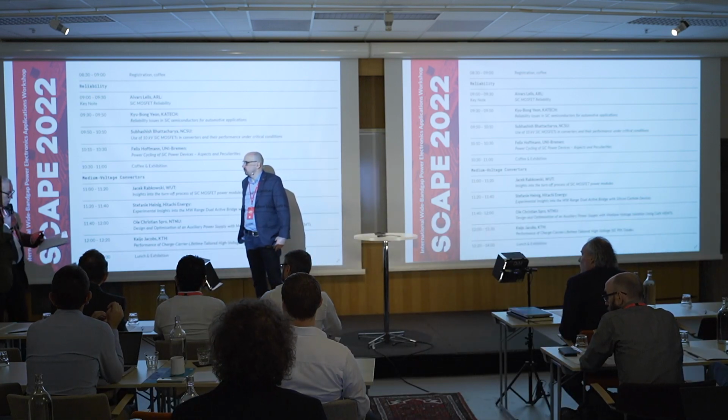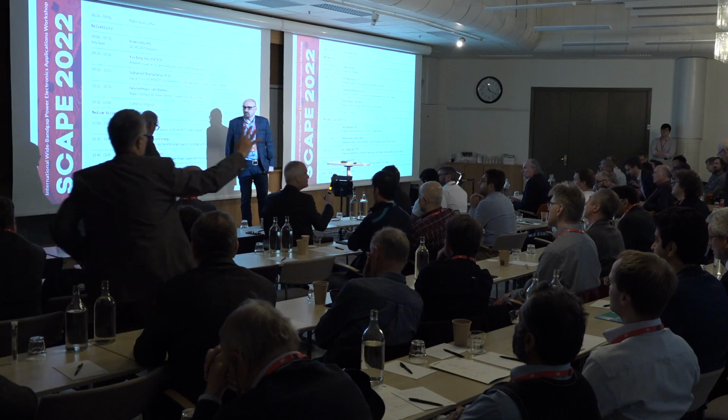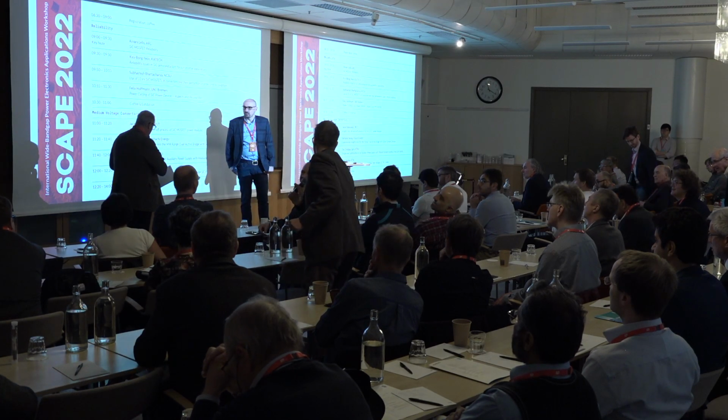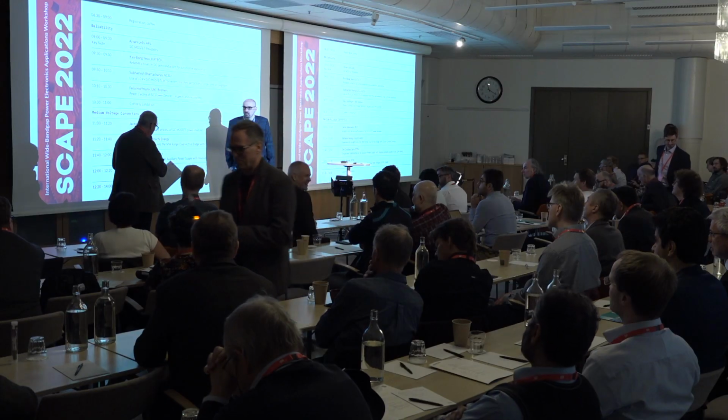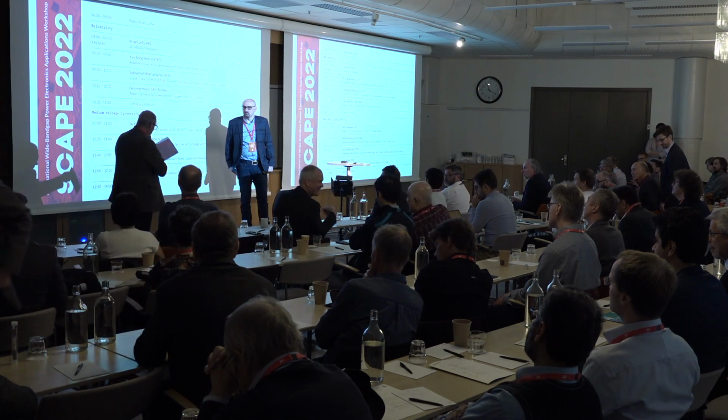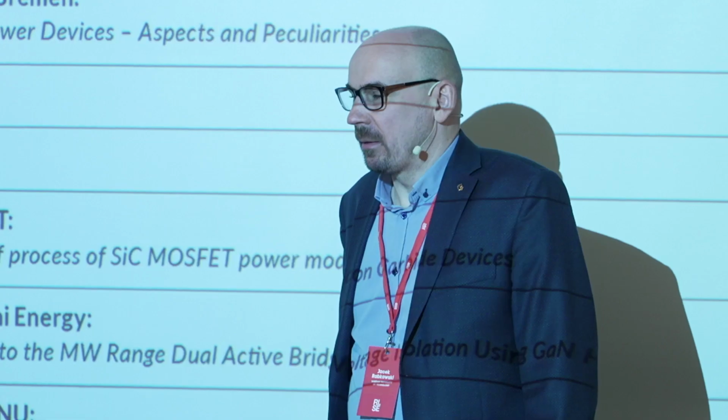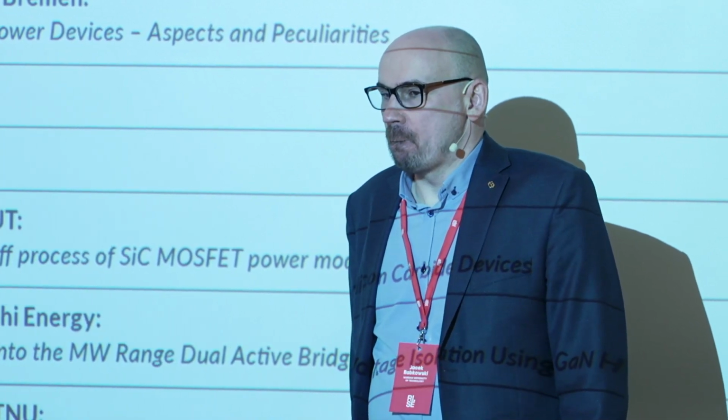I was just curious about when you measure the voltage, you also have a stray inductance. So the voltage you have, so to say, on the capacitor on the chip is not the same as the voltage you measure on the module. Do you see any problems there?